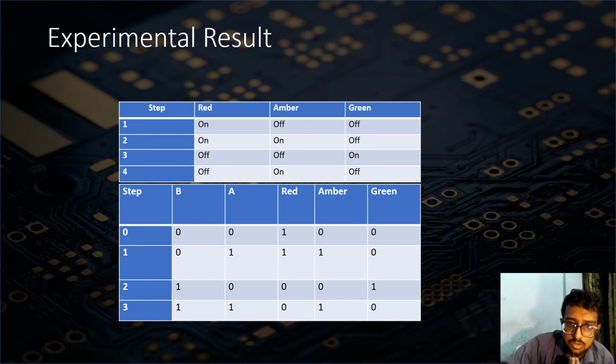If we NOT the A, inverting its logic level, A equals 1 and B equals 1 would illuminate the green. So we could use a NOR gate as an inverter by connecting its two inputs together, and feed the output of that plus B into an AND gate, and that would give us the correct control for green. Yellow here is considered to be B, and red equals A bar, and green is equal to red plus yellow bar.